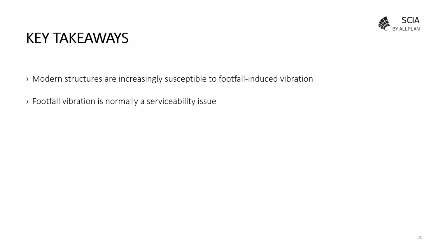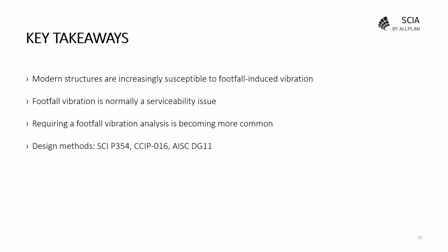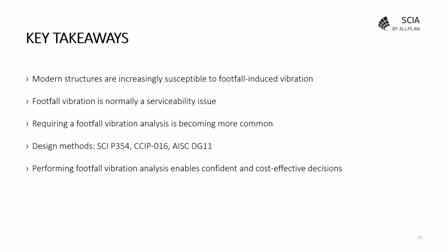Let's finish with some key takeaways. Modern structures are increasingly susceptible to footfall-induced vibration. Footfall vibration is a serviceability issue. Requiring a footfall vibration analysis is becoming more common. As previously mentioned, design methods are already available, and performing a footfall analysis helps you make more confident and cost-effective decisions.